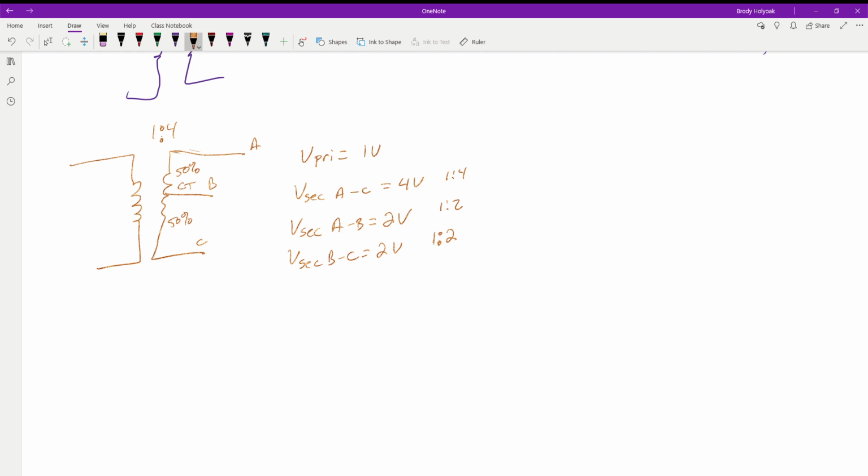And like I said, there were like 18 different wires coming off, and so each one of these different sets had a different voltage. So it had a black and brown combination that was 15 volts. They had a purple and a green, and that was 10 volts. And then they had a yellow and an orange, and that was 2.3 volts. And so what it was is they just had multiple taps.